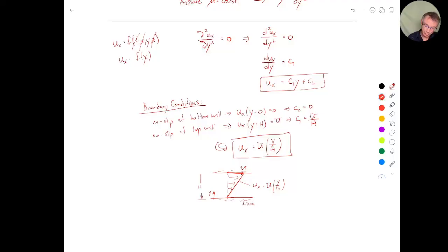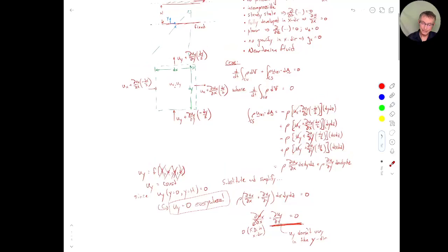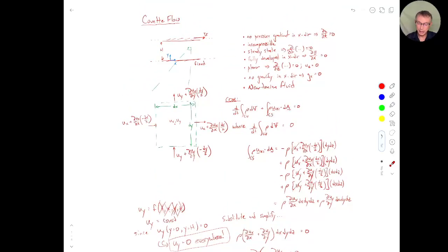So earlier in the course, we gave you a linear velocity profile for a Couette flow, but now here what we did is we actually derived it. And we derived it using conservation of mass and the linear momentum equation just applied to a tiny little control volume. We can do this same sort of approach for many different geometries. So for example, in this case, let me go back up here. I assumed that I was dealing with, let's say, no pressure gradient.